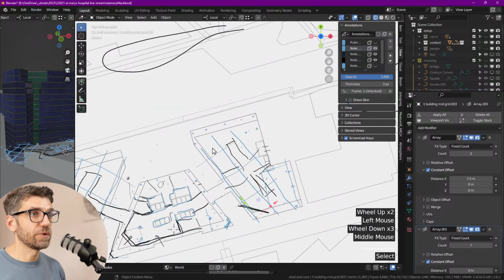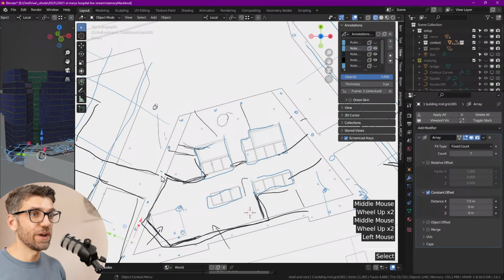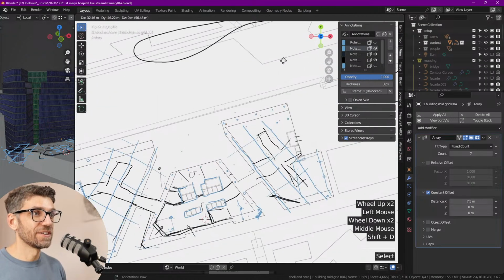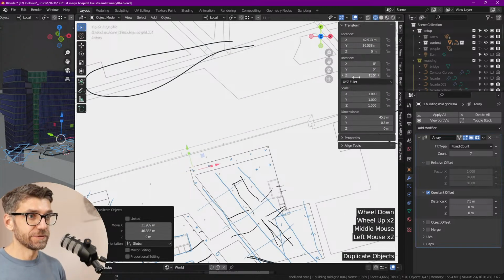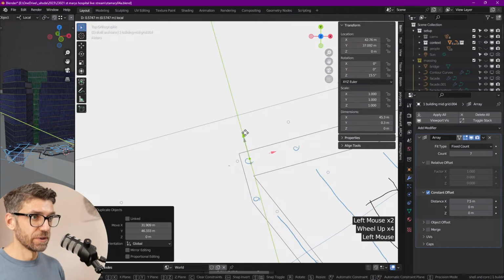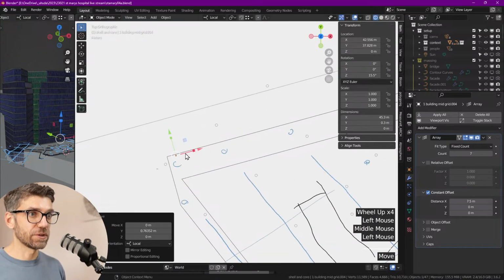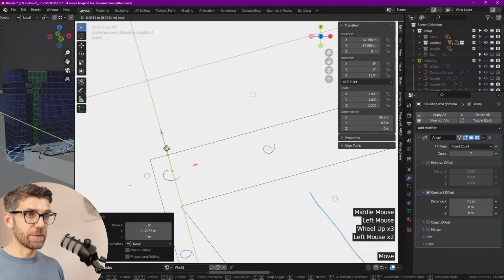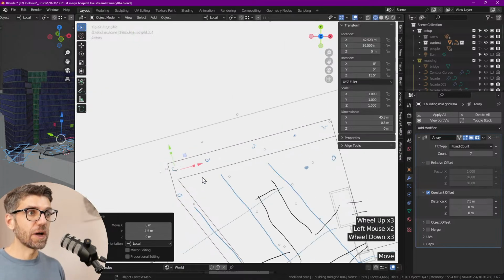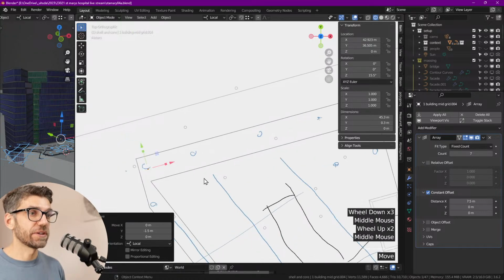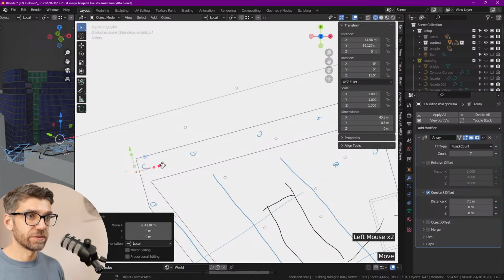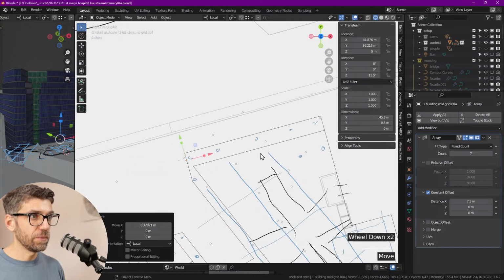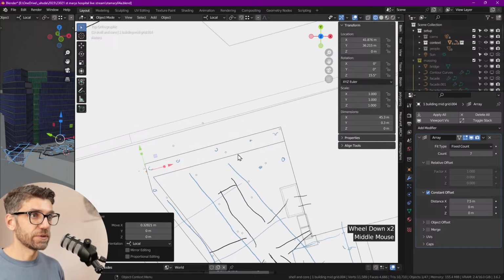First off, let's keep putting columns in. Not everywhere, but where we need to. So put that column in there, and this is going to get our 15.5 side angle. And let's do the same thing here. So I'm going to go as close to the edge as possible and then push that back 1.5 meters, so we have a nice alignment. Now that is going to align ideally with whatever these are doing, so that spacing might be a bit different. Well, it seems to more or less align. I'm not going to resolve it perfectly.